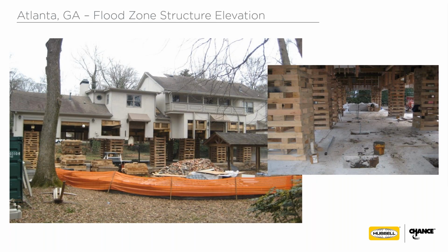This is another house raising example, case history. This was here in Atlanta, Georgia. We had a major flood in '09. So this was a large 2-story house that used to sit on a concrete slab right here. So the house was flooded, and they wanted to prevent that from happening again. The base flood elevation has been elevated over the years since the house was built. So in order to get flood insurance, they need to be able to get the structure, the living area, out of above the floodplain, the base flood.